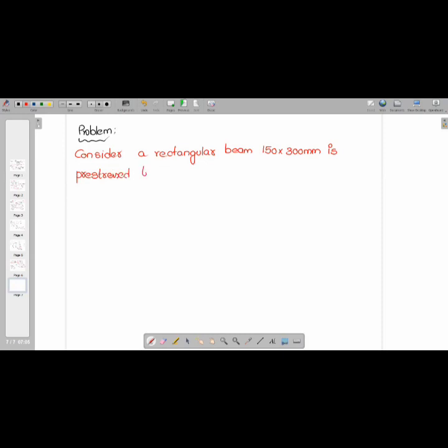Is pre-stressed by 4 high tensile wires of 5 mm dia, pre-stressed to 120 MPa.